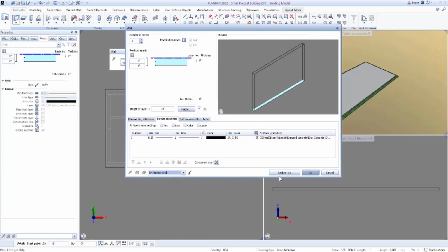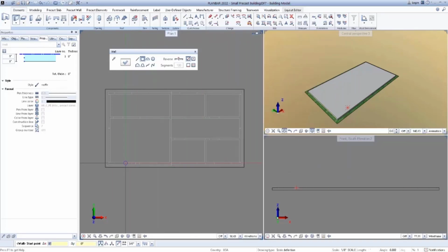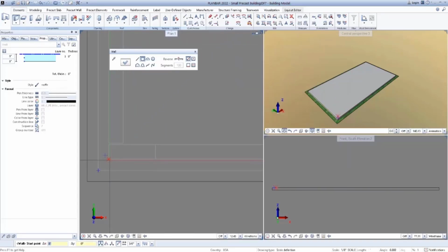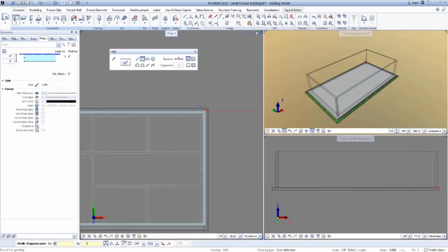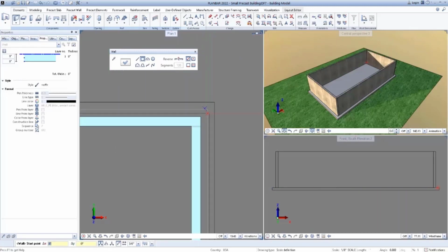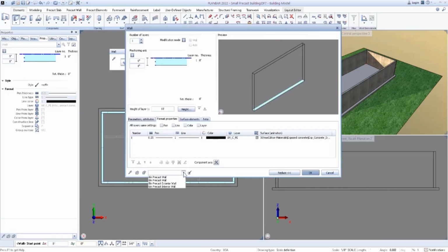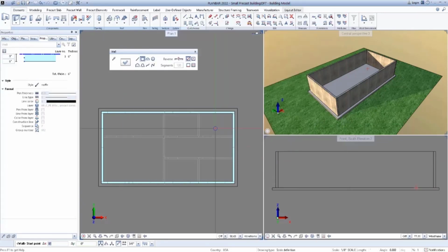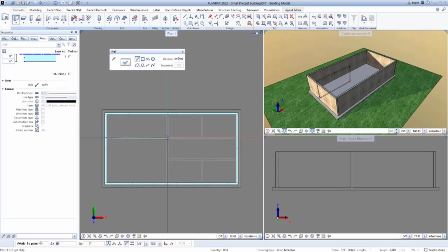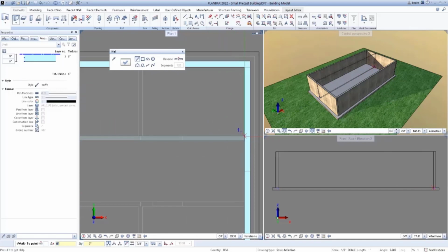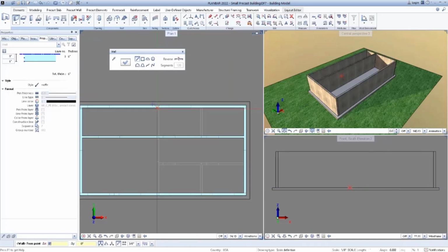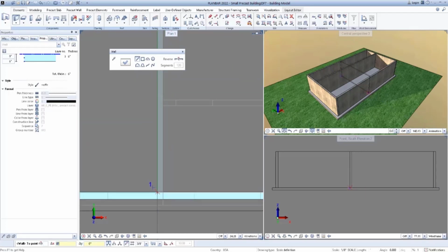Creating the exterior and interior walls will be a similar process as before, loading our favorite file that will apply the wall thickness and heights and then tracing the PDF line work. You can load different favorite files while in the command and switch the parameters for the interior walls on the fly. When modeling walls, we typically recommend adding a color fill so that it's easier to visualize where you have placed them in plan view. Later on, we'll convert these walls into precast.